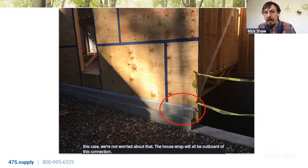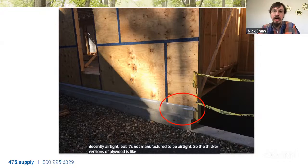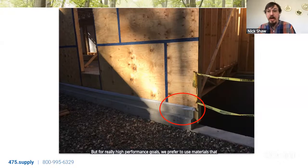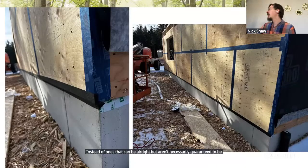People taping plywood, that's a pretty good home approach. Plywood can be decently airtight, but it's not manufactured to be airtight. So the thicker versions of plywood are a decent air barrier. But for really high performance goals, we prefer to use materials that are manufactured to be airtight instead of ones that can be airtight but aren't necessarily guaranteed to be airtight.